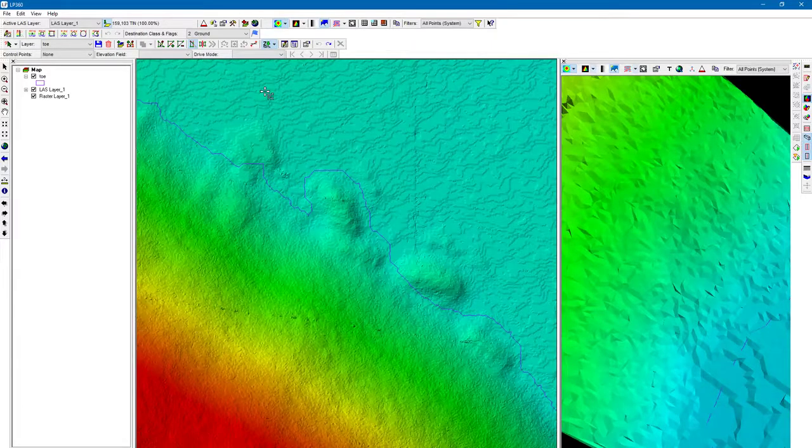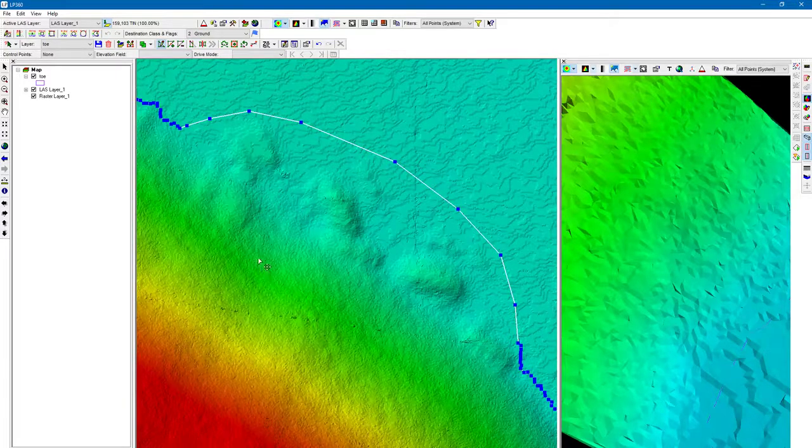Let's say you were wanting to edit a feature with this Reshape Geometry tool, and you weren't wanting to Auto Z, you wanted to interpolate the elevation in between the areas that you're editing. You simply just unclick the Auto Z, go ahead and draw your edit, and double click to finish. There we go. Let's say, well crap, I actually meant to Auto Z that section. Do I need to go back and redraw it? Do I need to undo and redo?